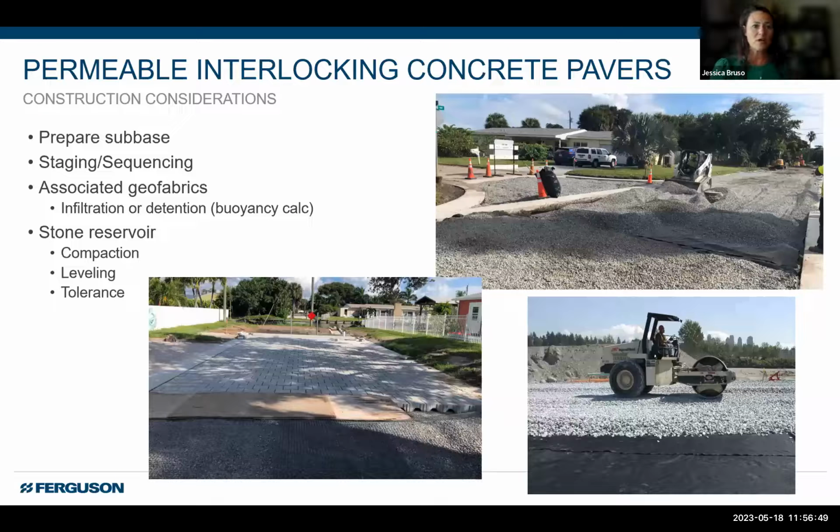If we look at our construction, again, sub-base is going to be very important, and having that geotech. Just kind of ping-ponging off Evan, what he said before, staging and sequencing is going to be very important for construction, making sure that if you're doing this in a residential area, that residents have access to their homes somehow and that they know what's going on. So that's really, really important. Associated geofabrics, this would come down to, again, what specific manufactured solution you are using and what is specified on those plans.